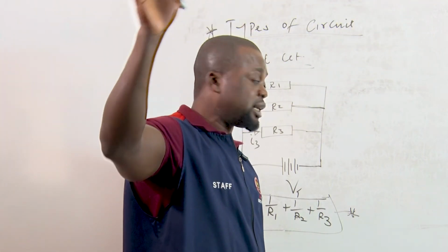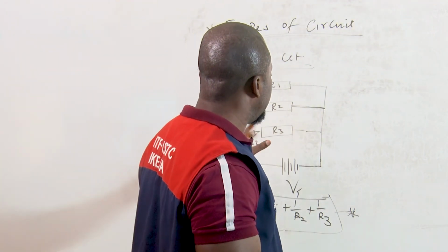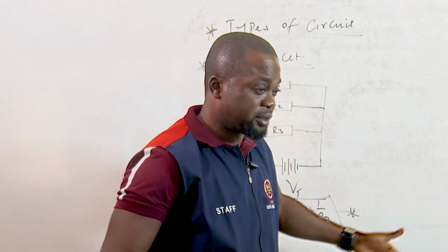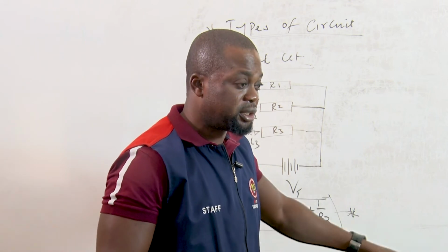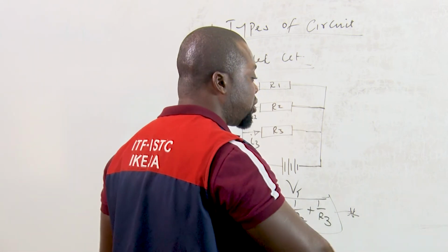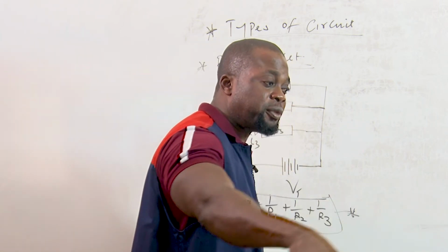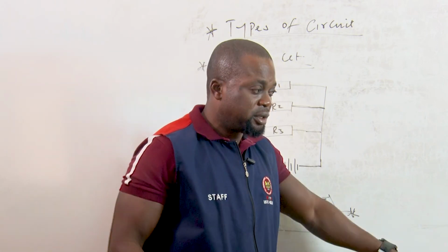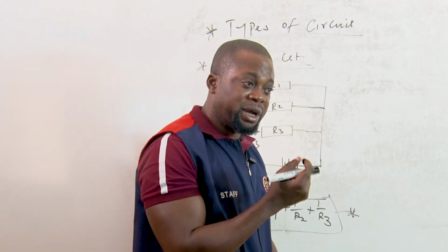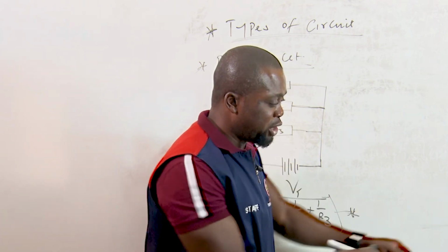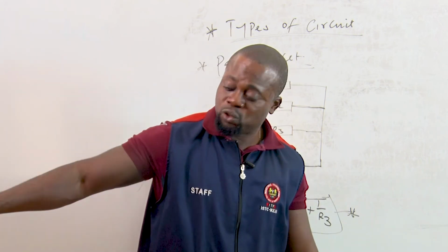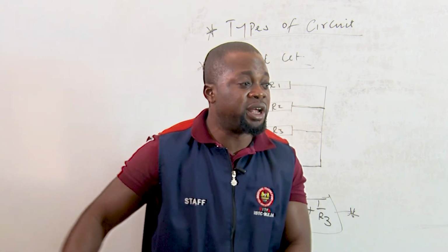When it comes to lighting arrangement, we should be able to carry out this parallel and series, or even sockets. At times, you can decide to connect sockets in a room and link them with a cable, looping from one to another to minimize cable. If there is a fault in one particular socket, it will affect the others.